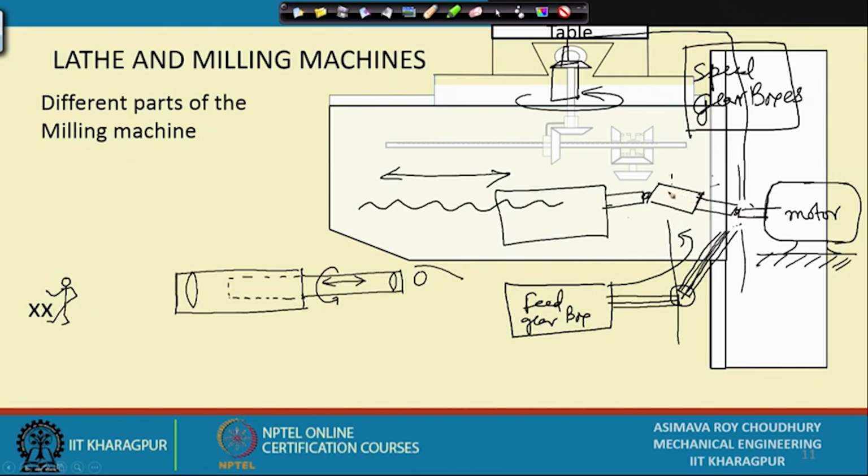So, if it rotates, there is still another problem. This might rotate, but still this is not rotating, because this is circular, that is circular, there is nothing to make this rotate. This is going inside this one, no problem, and that way length is getting adjusted. So, what we have to do is provide at least one or two keyways on this, or tooth spaces on this, and fitting teeth on this one, so that they will look like this. This one looks this way.